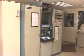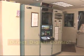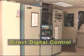There are several different types of process unit digital control systems. The differences between them are mainly in how the control function in each system is arranged. In one type of system, the control function is centralized. This means that all of the process control functions in the system are performed in a single location. This type of control is commonly called direct digital control, or DDC.